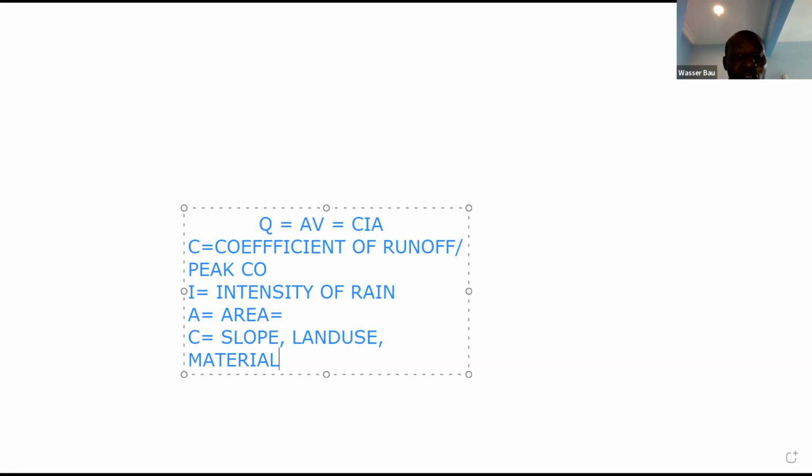So they have high hydraulic conductivity. High hydraulic conductivity means once water falls, all of it will just go into the ground, and then it will flow as subsurface water, thereby not causing erosion, not causing havoc. But in some of these erosion-prone areas, you find that the underlying soil will refuse to take the water. So it is a function of the material and the slope, and the slope is also a factor. If a place is like a bed, a basin, when water falls, the water will just stay there, impounded. It can't go down.